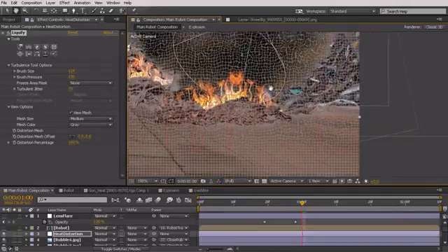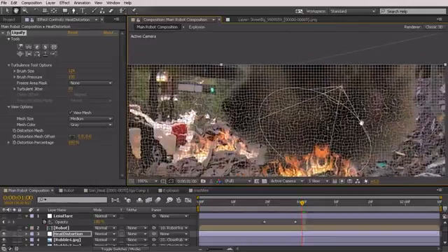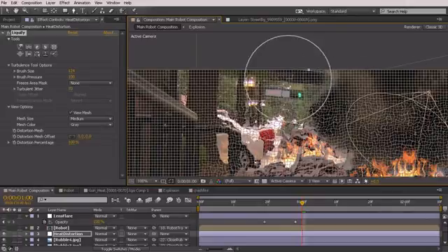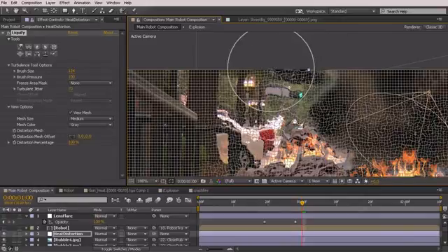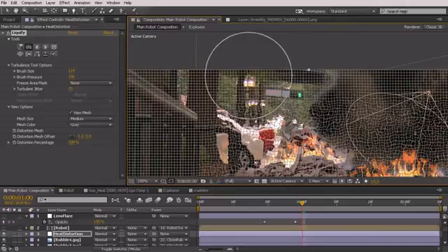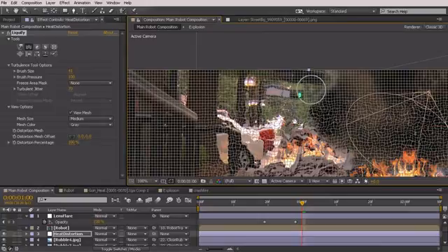Okay, so I'm going to move this up and over here, and it looks like we probably need a slightly smaller brush up here, because if you distort this at the top, notice how that mesh pulls this down and we're seeing behind our image, our back plate, and it's just a black background. So I'm going to undo that. We want to make sure we preserve that upper edge. So I'll just come in here and turn the brush size down, and then we'll be able to add some distortion to these upper areas without affecting the straightness of that little top line there.